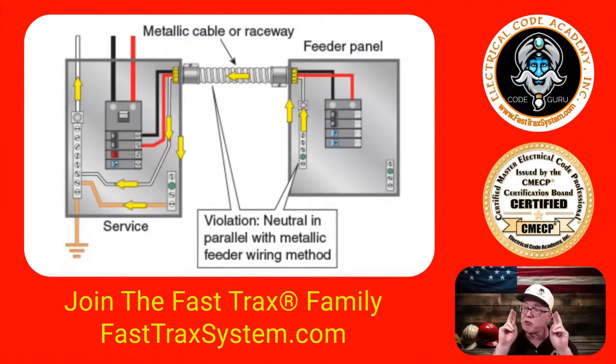You can in specially made MC with 6-gauge conductors and less, but that's not what this is. Okay, so all of this is listed in 250.118. I encourage you to pause the video, go look at it, and see the different allowances. Now, if this was rigid metal, intermediate metal, if this was EMT, all of those types of raceways and tubings are listed over in 250.118.